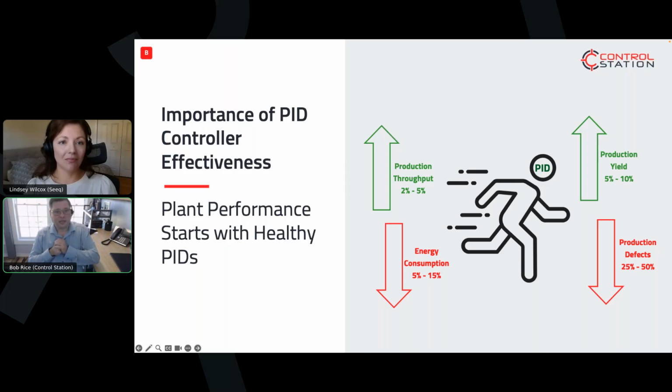We used that minor improvement in variance, moved the set points, and were able to decrease energy on those loops by 1 to 2% pretty much consistently. Very little effort, fairly high return. So the dollars are there. They tend to be a little bit tricky if you try to look at it from an entire facility standpoint, but if you focus in, the opportunity is there.